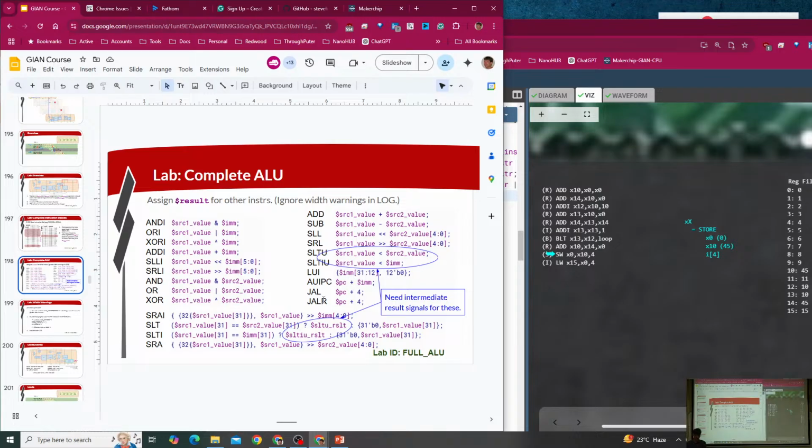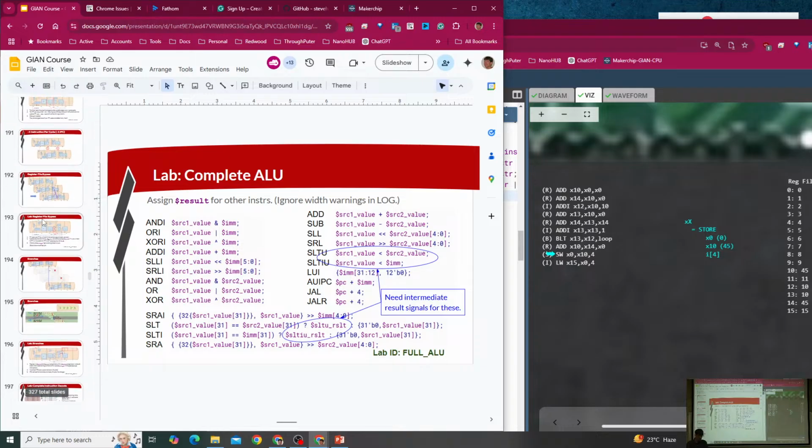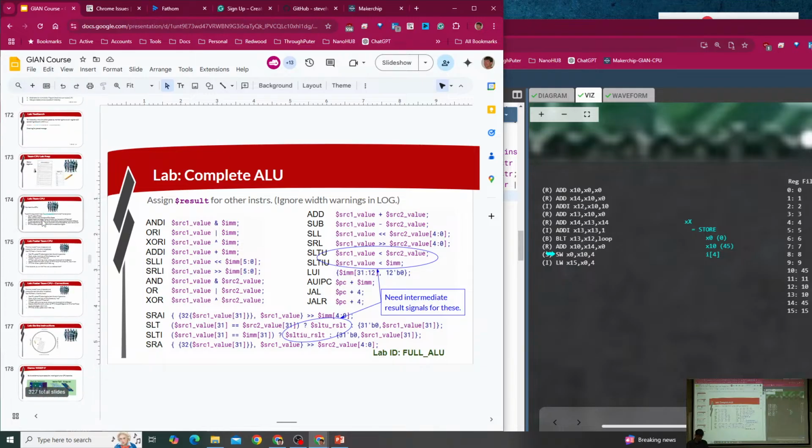The register part says that the address we're jumping to, the base address, is coming from a register versus coming from the PC. In either case, we want to link the program counter for the return. So in either case, we write the destination register with the PC of the jump +4. That's the return address. So when the function that we're calling does a return, it has that return address. We saw that when we looked at the assembly coding, right?